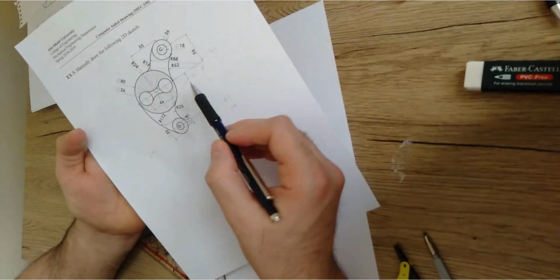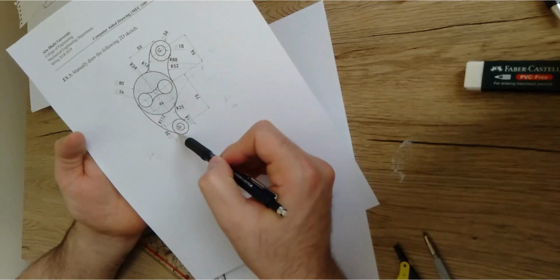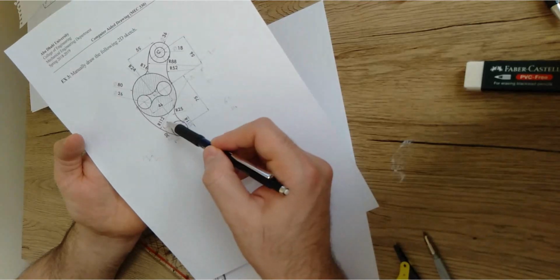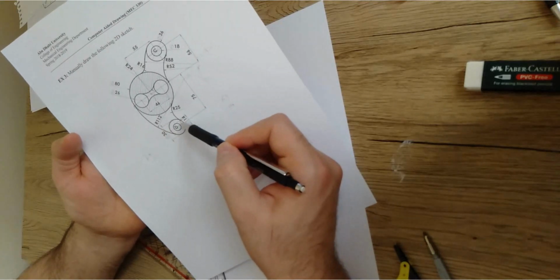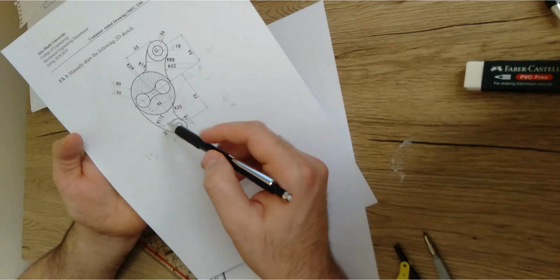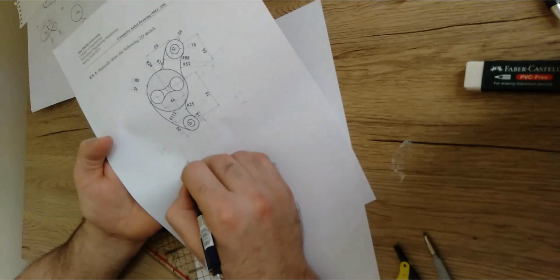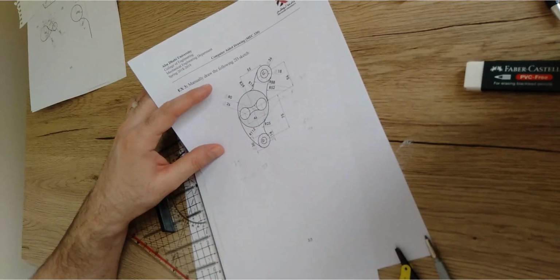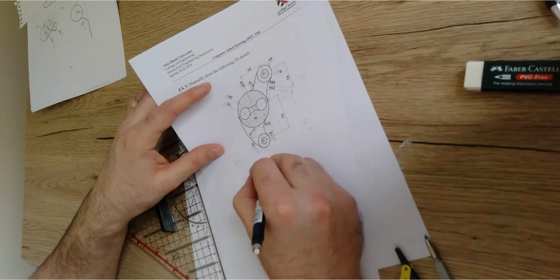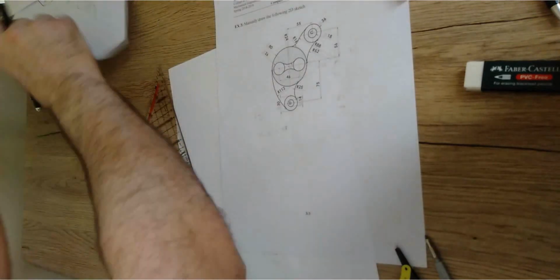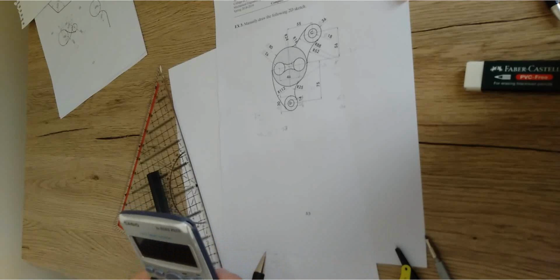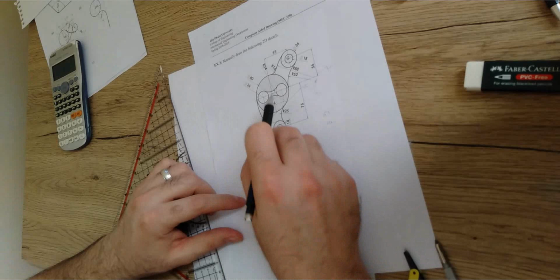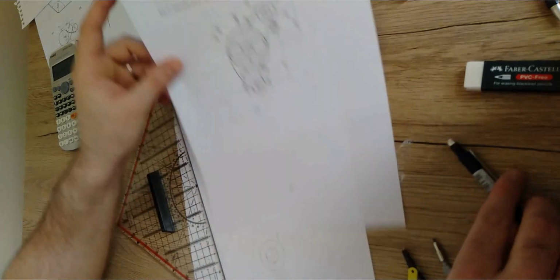How about the small circle? The same. If you try to move from the center to the center, you will not go over the tangent point. So what does it mean? It means that we have to subtract 112 minus the radius of the small circle here, which is 15. So it's going to be 112 minus 15. This gives us in total how much? Like 98, right? Or 98 or 97, I think. I'm very bad at calculation. Let me see. It is 100 minus 15, so it's going to be 97. So from this center, I'm going to open the compass to 97, and from this center, I'm going to open the compass to 72.